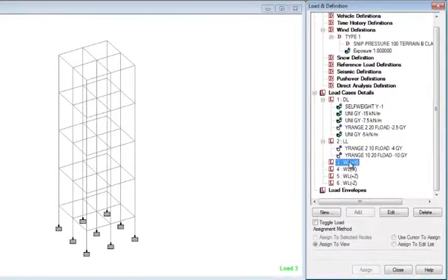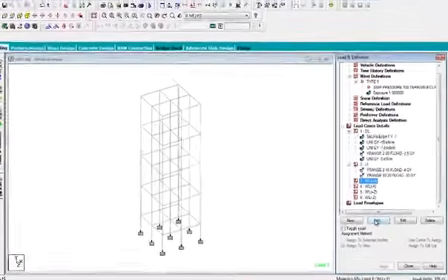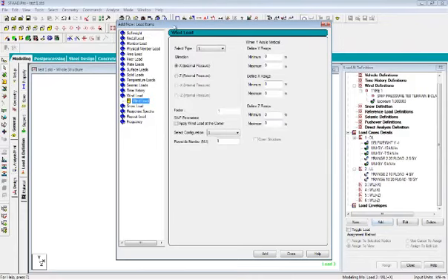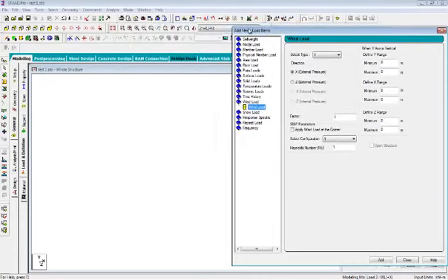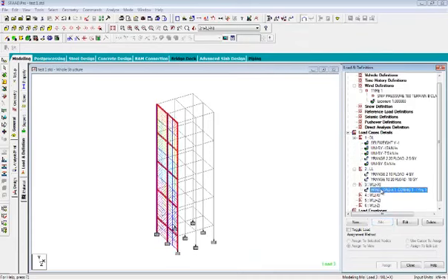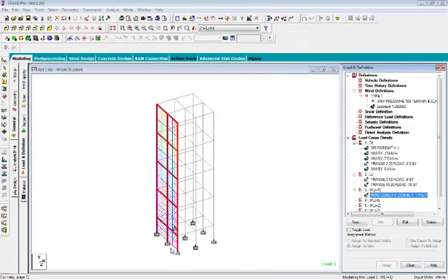So first is the wind load in the positive x direction. Go for add, then the wind load, then let me move it to the side and show you the difference of what happens. External pressure, and if I select it as add, close. Now you see the external pressure has been added, but you see one thing.